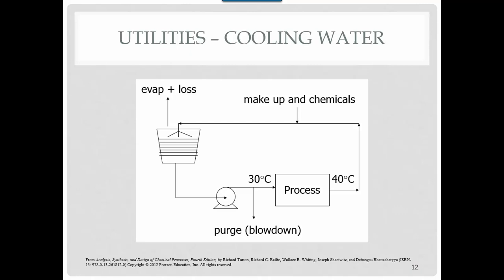Now, cooling water. Cooling water is going to be very similar, but unfortunately with cooling water, you always need to be adding chemicals, treatment, so that you don't end up with, I don't know, algae growing in it, so that it is not corrosive inside your lines and so forth. So you're always going to have to take your system, and it may be a closed system in one sense, where the water is just circulating through your process, but you're always going to have evaporation and various kinds of losses. And so you're going to have to add some water makeup and some chemical makeup to this.